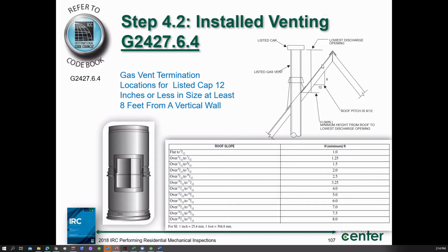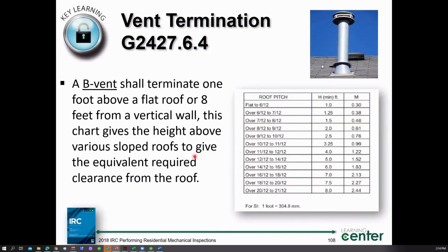Yeah, basically we have a situation where if I had a roof obstruction or a wall obstruction, when wind hits a building, ladies and gentlemen, you know what happens? It will create these currents. We call them eddy currents, if you will. These downward draft currents. When wind hits the wall, it'll circulate and downdraft through the vent. We get these circulating velocity or vortexes around obstructions that could downdraft into the vent. So that's what it's all about. Yeah, good. So now you're aware of the vent terminations.